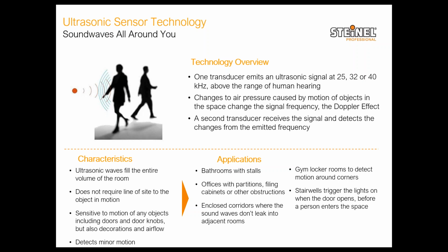And then the other characteristic is that, as I said, it's a very sensitive technology. So the slightest movement, a door handle moving, a doorknob turning, any decoration, any artwork hanging from the ceiling, even the airflow from HVAC units can trigger an ultrasonic sensor. Even the smallest vibrations can set off an ultrasonic sensor.